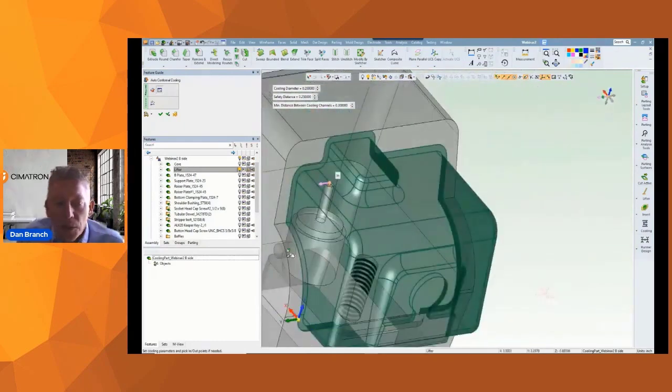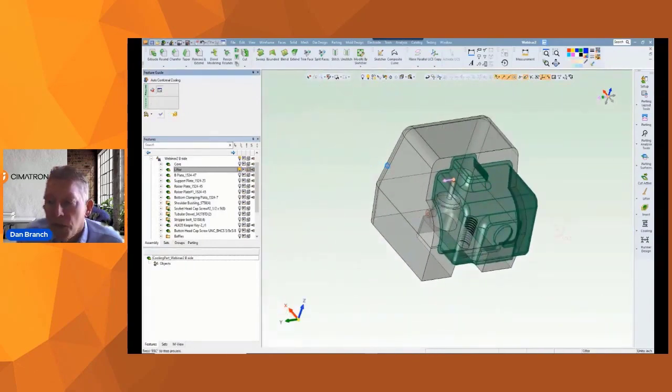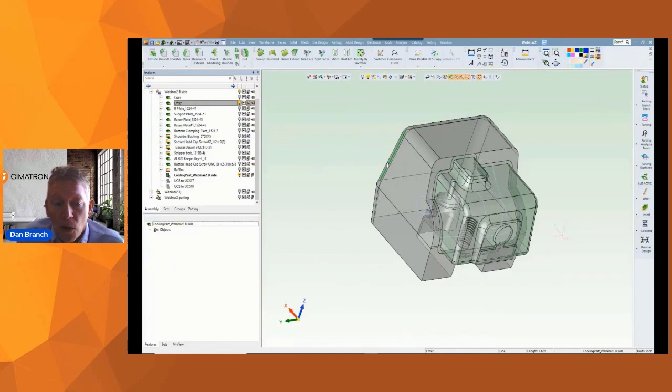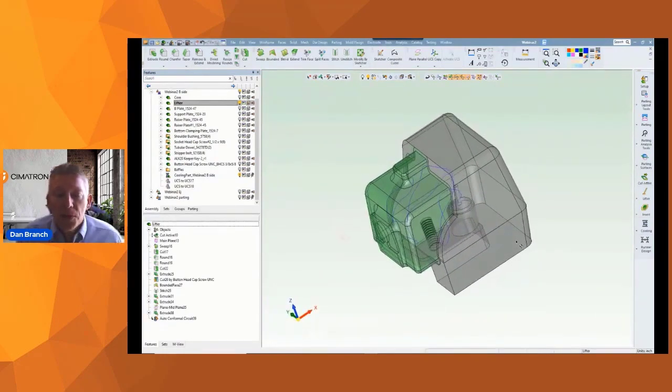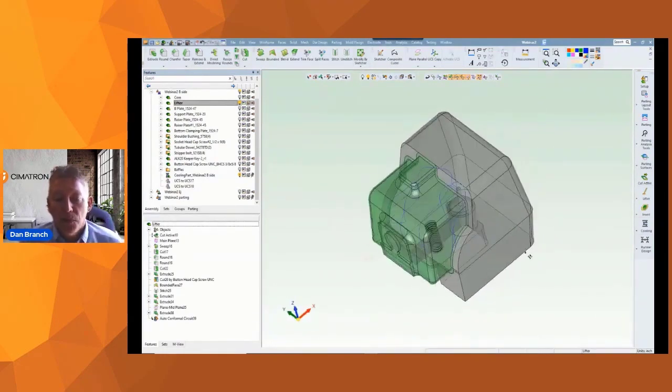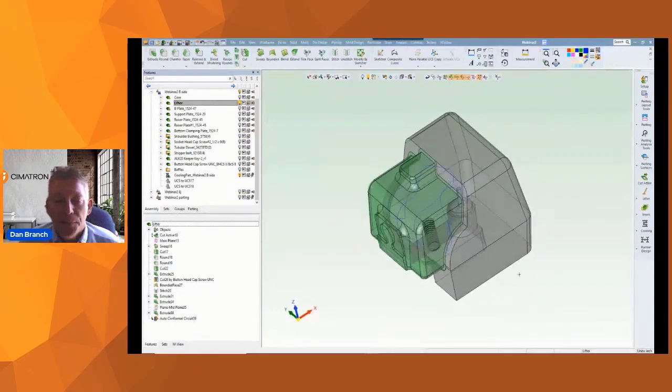Now, selecting where the cooling channel starts and ends isn't a required step, but in this case with the lifter, I know where the water is coming up from. So those are inputs I want to provide as well here. So based on those parameters, I've been given a blue curve, and that is the path that I could then choose in conformal cooling to lay a channel on.